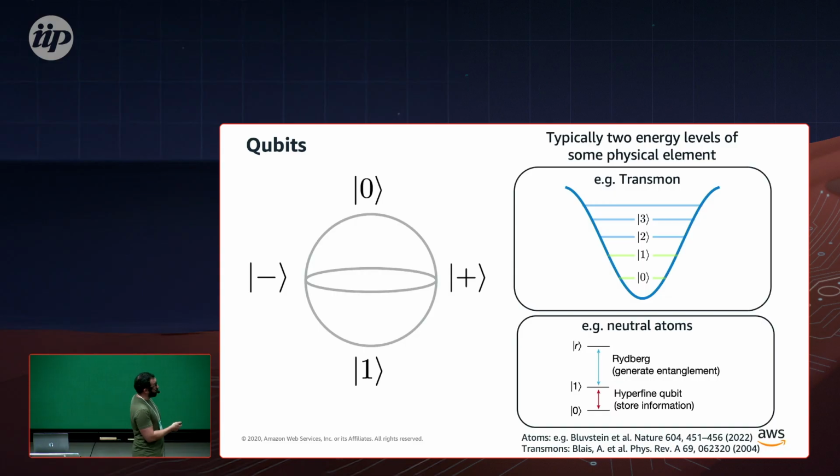I told you about one way to form the qubit, which was this transmon, right? So we have this harmonic oscillator. But now, because the Josephson junction is not harmonic, it's an anharmonic oscillator. So the gap between 0 and 1 is larger than the gap between 1 and 2, which is larger than the gap between 2 and 3. How different the gaps are is like 200 megahertz. So this gives the scale of how fast you can do the operations. That's the main qubit for superconducting qubits. There are other qubits as well you can build, but this is one of them.